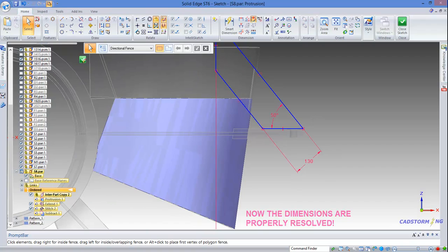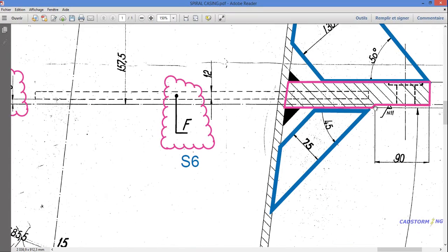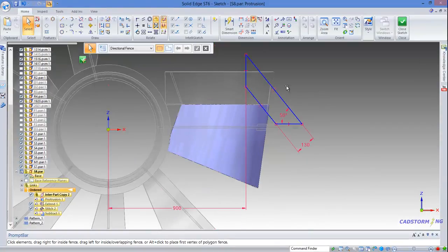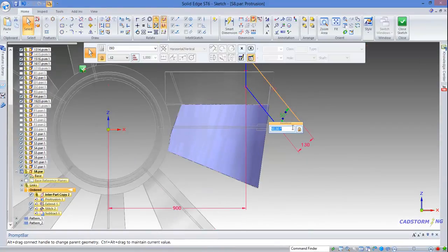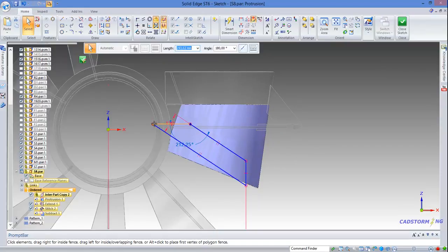And for the bottom stiffener we will align this edge to the edge of the cutout on this mounting plate, and we will have a 45-degree angle and this 55 millimeters dimension. Okay, so we have to make this dimension driven, so we can select this endpoint and move it underneath like this, and we do the same for this one.